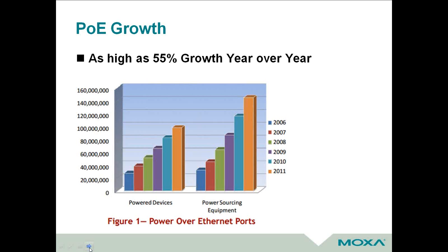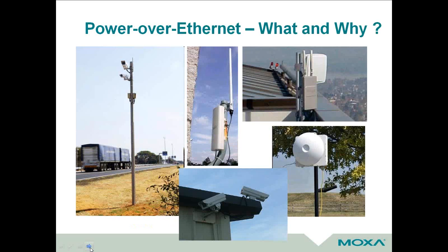And well, why and what, I guess? Why would you use PoE? What's the big deal, really? And it is actually a pretty big deal. With most applications nowadays, you will see almost 100% adoption rate on wireless and cameras for PoE. And the reason is simple. If you put a camera up on the top of a pole and you plug it in, it's just a hassle to run extra power wires all the way up that pole just to power that device.